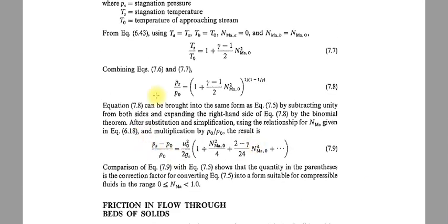Mach number is a characteristic which is used to calculate the velocities in the air when the system or solid body is moving at very fast speed in the compressible fluid. So that can be calculated by the Mach number. Okay, so when Mach numbers are very high, meaning bodies are moving at very fast speed, then you have to use this formula, where this is the Mach number. So this can be calculated by using this formula. You can calculate the pressure difference in front of the streamline body. So this will create some amount of form drag.